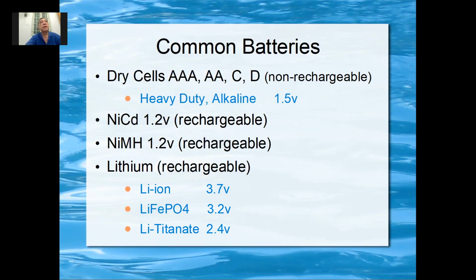I have some of these batteries. I don't even want to use them, because it's 1.2 volt, and if you use 2 pieces, it's 2.4 volt, and the device expected 3 volt. When you put it in, after a while, it tells you battery low. So some devices that can operate down to 2 volt are okay, but some just cannot.